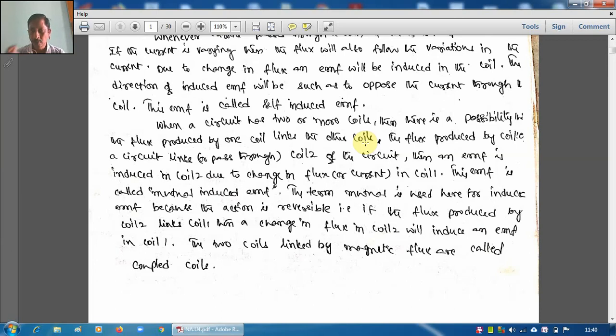Because of the placement of the second coil nearby to the first coil, EMF is induced in the second coil also. If we use that EMF by closing a circuit, automatically current flows and there is power in that circuit. Now, how is power transferred from the first coil to the second coil?